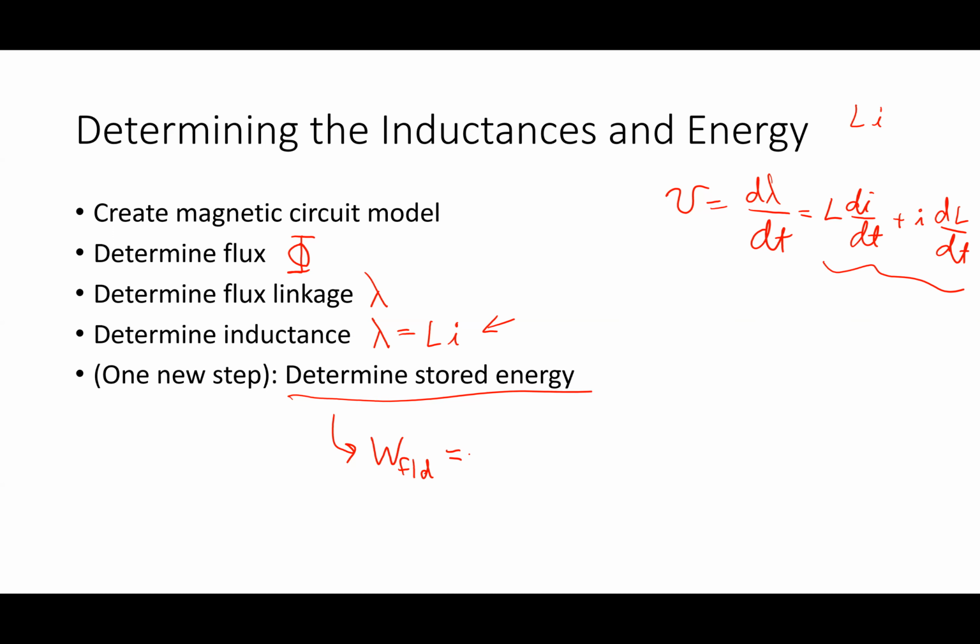What's that equal to for an inductor? 1/2 L i squared. And that's not necessarily true. That's true for a pretty simple inductor, but not one that can saturate and all that kind of stuff. But under the right assumptions, that's at least true. That would be true for a lossless inductor. If I had losses, then 1/2 L i squared is still the energy I store in it, but there's also an energy lost over time that I would have to factor in.